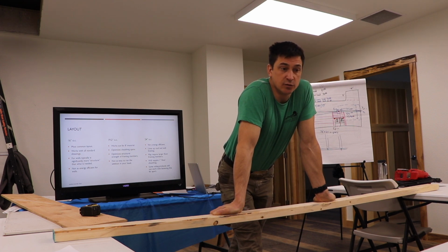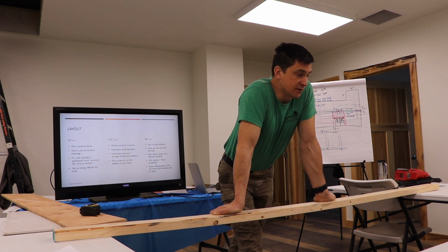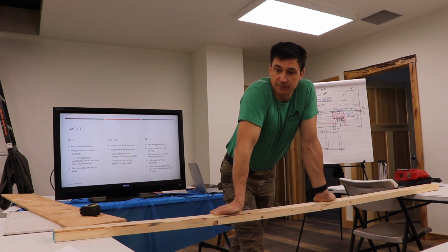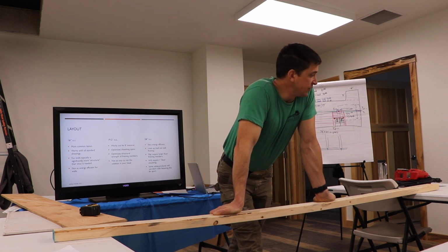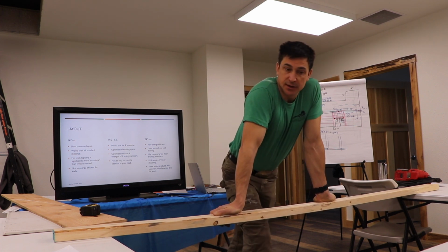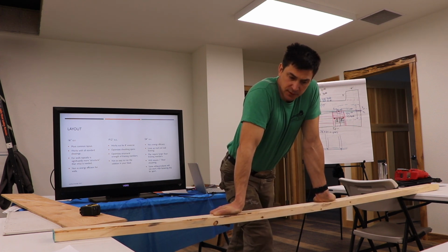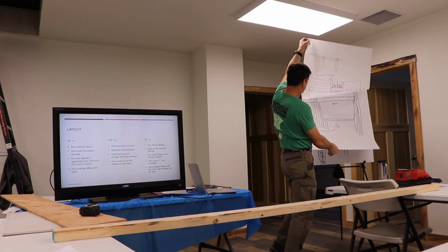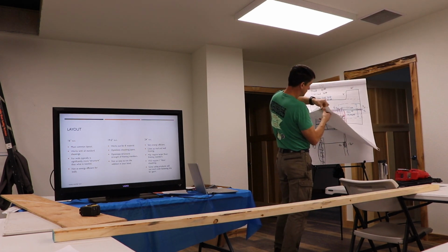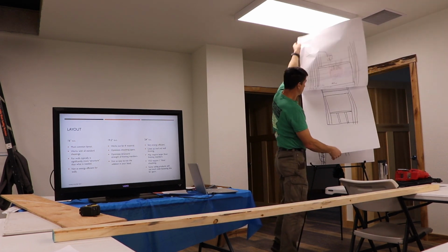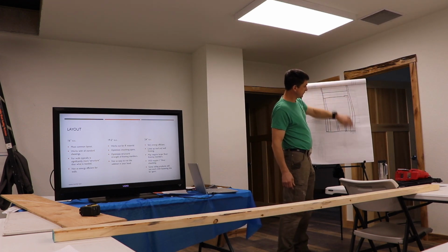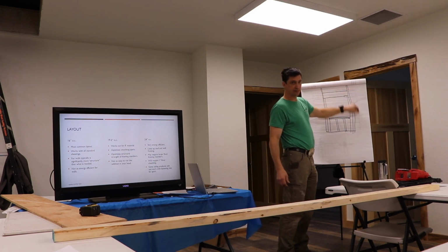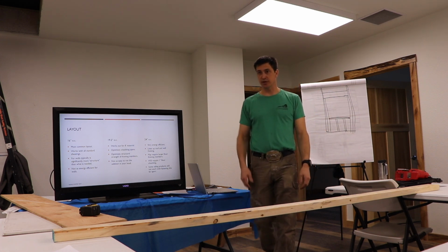Anyway, my dad, when I was a kid, well, we had a relative, still have a relative, but he was all he did was framing. He had him and 4 guys, and all they did was frame. And if they had a stud come, like for a window, like a jack stud, so if they have the king stud and shoulder stud and the layout has a stud less than 3 inches away, they just leave it out.